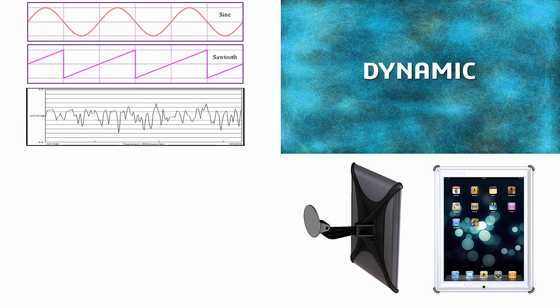While static analysis relies on your component having static equilibrium and static loads, where the only response of the component is through structural deformation, dynamic analysis allows you to put in vibration loads or time varying loads. There are different kinds of vibration loads that we can put in. We can put in time varying sawtooths such as these, or we can put in full on harmonic loads such as this little sinusoidal input.